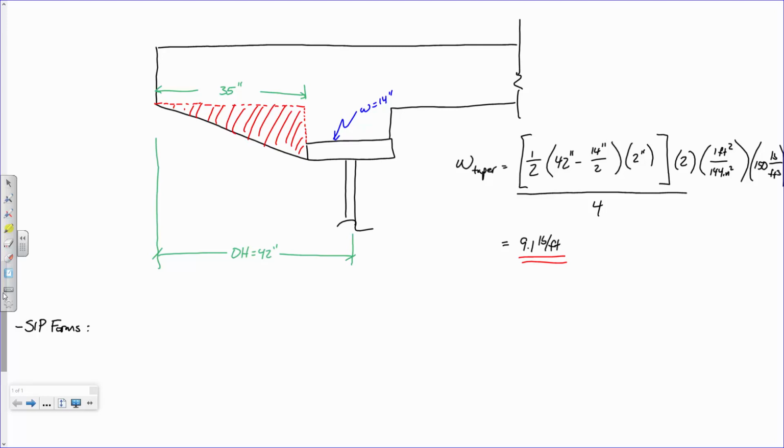Okay. There's one more load that needs to be assessed, and that's SIP formwork. Now, SIP formwork is essentially the metal deck pans that are used to cast the deck. Now, I'll be frank with you. Some states do not like the use of SIP formworks. West Virginia is a state that doesn't mind them. There's a perception that because it's metal, it's just another thing that can rust. But okay, maybe there's some truth to that, but once the deck is formed and cured and composite and hardened, who cares? And if you're getting some sort of chloride penetration that's starting at the very top and it has penetrated completely through the deck and it's starting to corrode your deck pans, you got a couple more problems than just your deck pans.